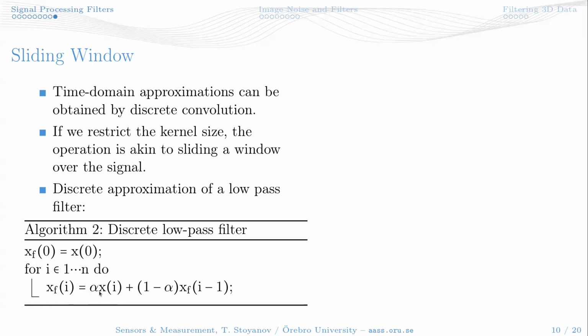And the first part is the actual new signal, so it's going to be a completely flat line. The signal is never going to change if alpha is 0. If we set alpha to 1, then we just pass through the signal without performing any filtering.